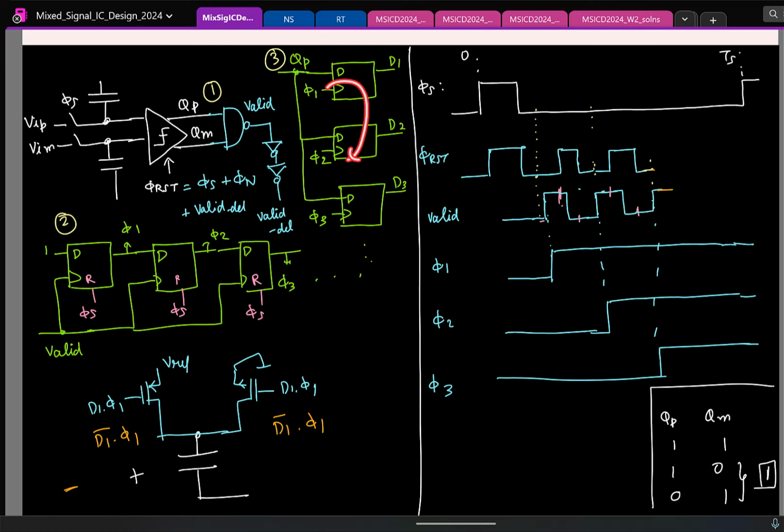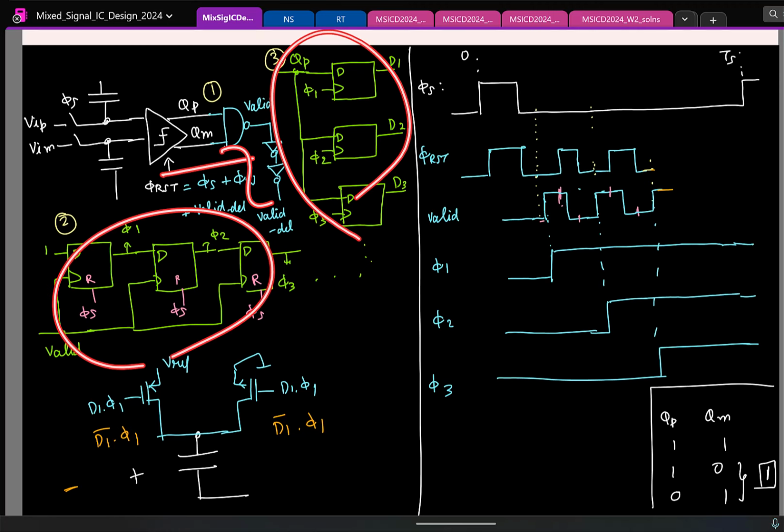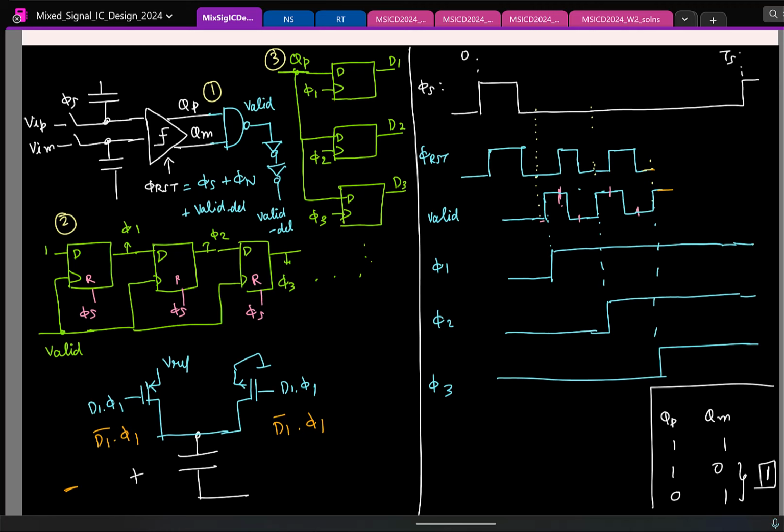It depends on the delays you have, the comparator delay, the time taken for the capacitor to charge, everything that will impact. It comes to comparison delay plus the valid delay. Correct, comparison delay, valid delay, but remember that by the time you should also finish doing these things. See, there are two things happening in parallel.